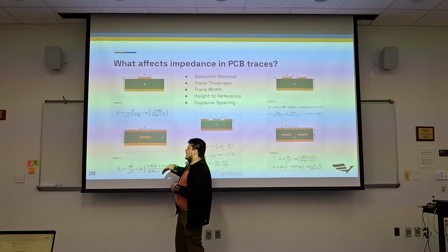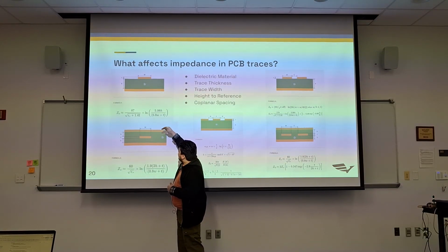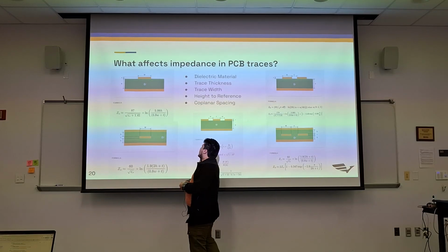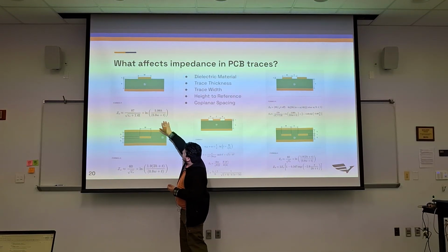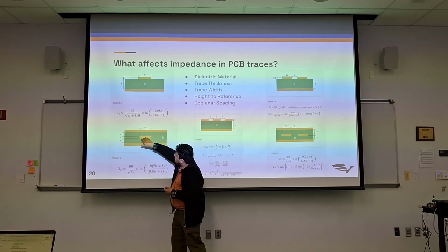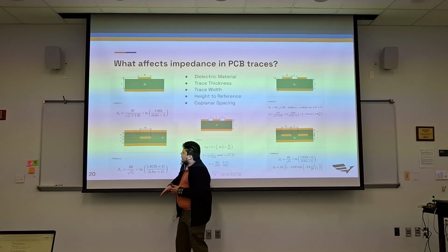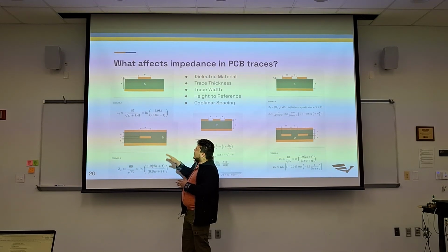So you're probably not going to encounter this, at least in formula, where you have component, ground, ground, signal, ground, ground, signal. But this is where it's embedded. So yes, you could see this in a 4-layer board where you have components, ground, your 3rd layer is a signal, and then your 4th layer is a ground. So it is possible. It just has slightly different math.